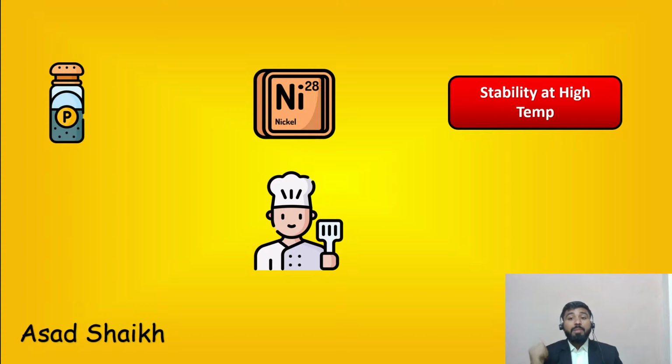Soft packing material. Now packing material is something which is a little bit trickier than this. I'll just give you thumb rules right now because we're running short of time. See, for packing material, you need to see the fluid also. At the same time, temperature becomes very important. And third is, which Mayank mentioned, fugitive emissions, because if that fluid comes out from the packing, it is also a big issue for you. So these things come into picture.